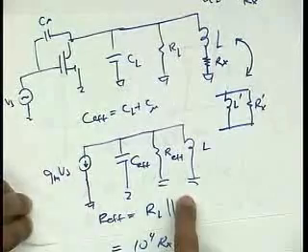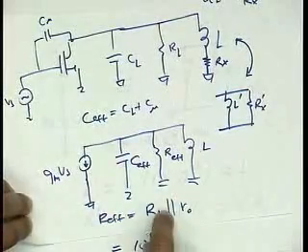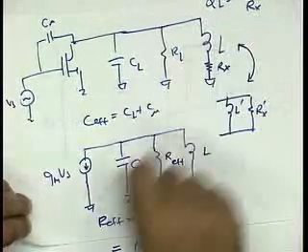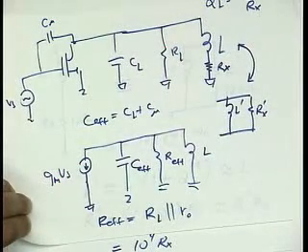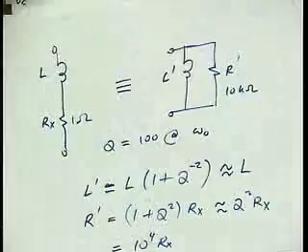Okay, so this transformation, a very important point. I'm glad you asked this question. It only works at one frequency. So at the frequency of interest, the reactances are equal. If I move away from that frequency, these do not equal each other. Okay, that's a very good point. And that means that when I have this equivalent circuit, and I go from here to here, this equivalent circuit is only valid near the frequency at which I did this transformation. All right, good question.